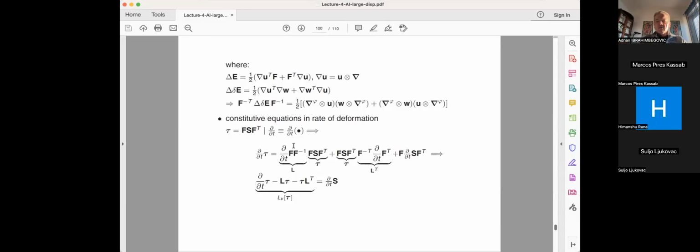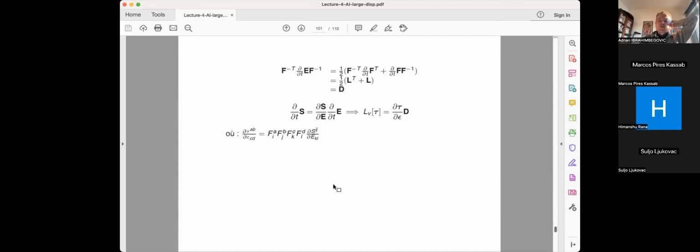But it's rather clear when you have to do this transformation, starting from the stuff that you already have in material description. In my mind, this could be worked out very easily, just like packaging. Basically, you packed it one way, you have only S dot, but for some reason you prefer tau, and then you have to work a little bit more. So what would be the reason to prefer tau? Well, the final thing, I think, and that was the mistake, as I said, in a very famous paper by Bathe, Ramm and Wilson, where they did this updated Lagrangian formulation. They missed that the constitutive model has to be changed when you're doing this, rather than the one from the total Lagrangian formulation, because you have this transformation from one to another.